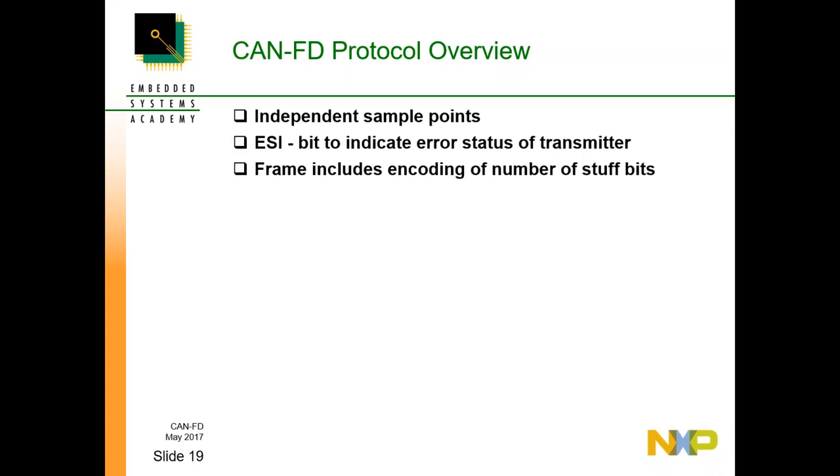However, all CAN controllers should be configured for the same sample point. All CAN controllers have two error states, active and passive. In error active, the controller is fully participating in communications on the bus, and in error passive, the controller cannot transmit error frames. A controller enters error passive mode due to errors transmitting and typically indicates a faulty configuration or hardware problem.